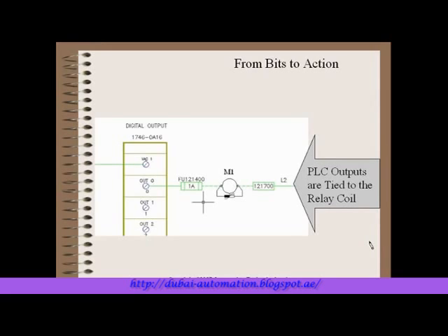Likewise, on the other side, we have our PLC outputs, which are a different type of card that interfaces directly to our relay, motor contactor M1. You see it has a surge suppression device around it to protect the PLC output. Also a fuse, it protects the output. But generally, the main thing you have here is this output directly from the PLC that goes to a relay coil to be able to operate some kind of real-world device.